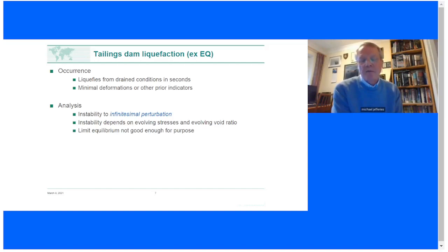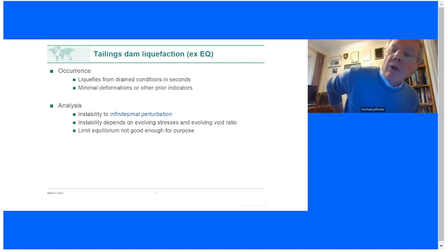We all do labs, and there'll have been a structural lab. One of your experiments would have been a buckling of a column. And static liquefaction is analogous to column buckling. What is happening is we get to a particular situation of stress, and the soil is in a condition where there's a lower energy deformation mode, and it will just flip to that, literally with a butterfly wing.